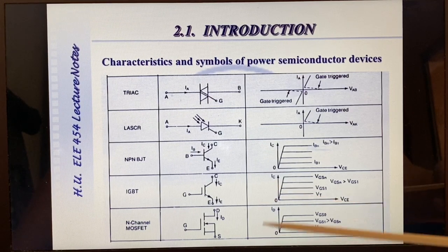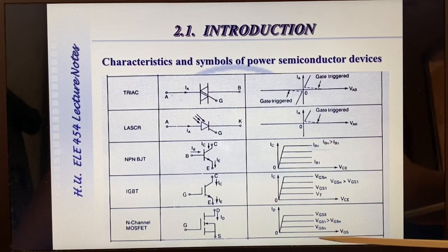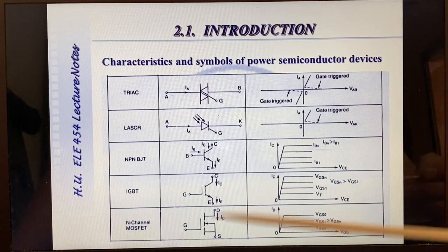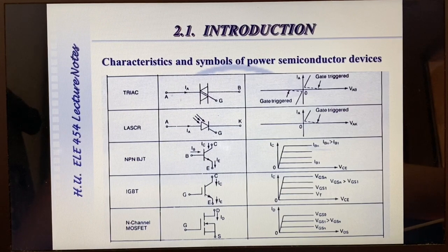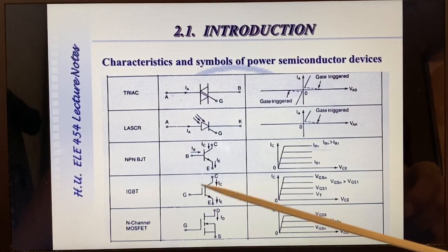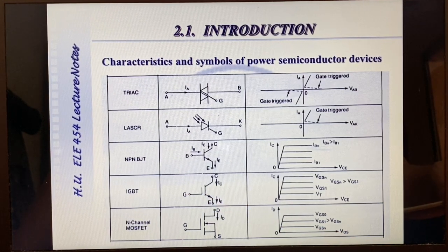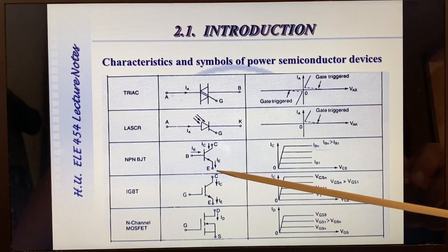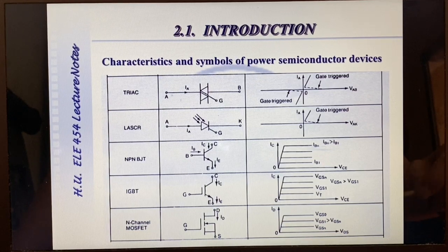And so an idea came to combine the two, BJT and power MOSFET, in order to obtain an insulated gate bipolar transistor. Here, the input is like the MOSFET, a gate emitter voltage control signal puts the device into conduction, but once in conduction, the current flows through the collector emitter as if it were a BJT.